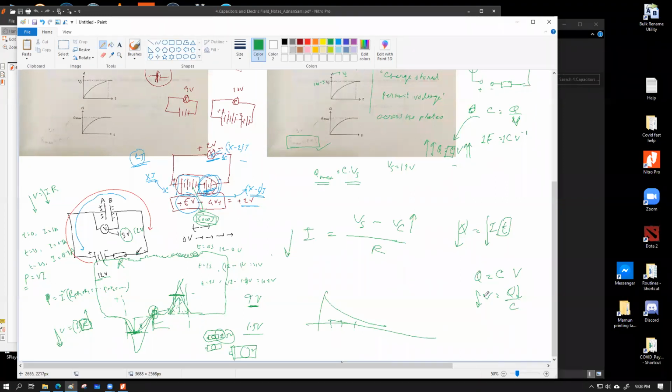So less current is going to flow in the later seconds compared to the earlier time, because the effective EMF of the circuit is gradually decreasing. Since current is flowing less, the voltage gain rate of the capacitor is also becoming less, because now within the same amount of time, less charge is transferred to the capacitor.